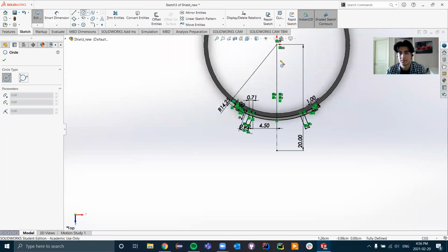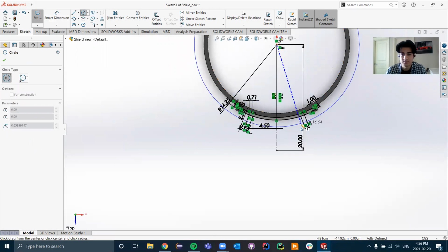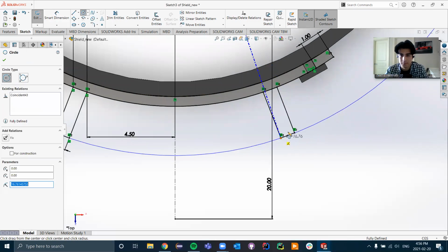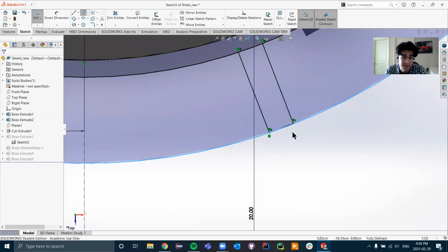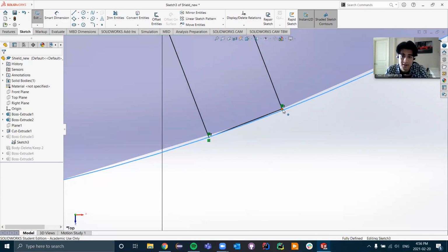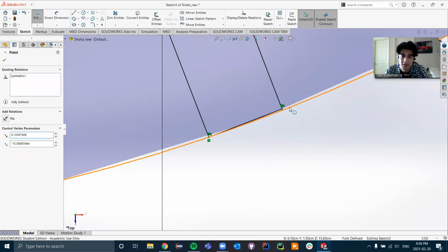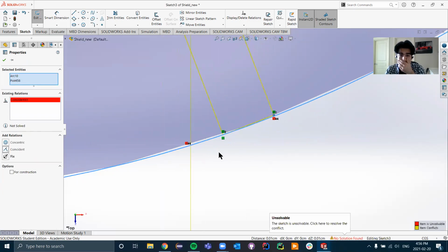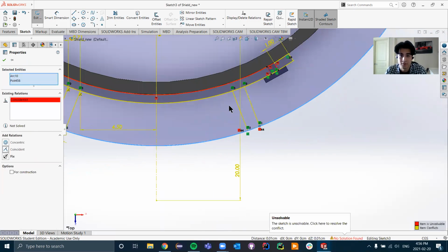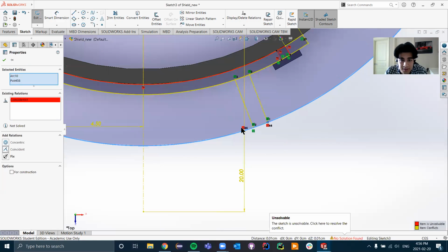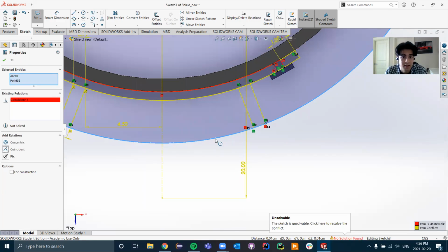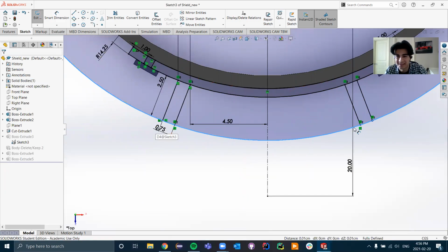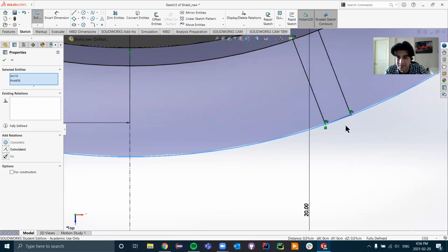So I'm going to go from the origin and essentially click on one of the vertices now. And you'll see why I did this. We can essentially bring this one up and make it coincident. Now it's overdefined, and that's because of one of our relations. So let's see, what is a relation that ruined it for us? I think the previous method was better. We'll go back to that, just so that we don't have to deal with the hassle.